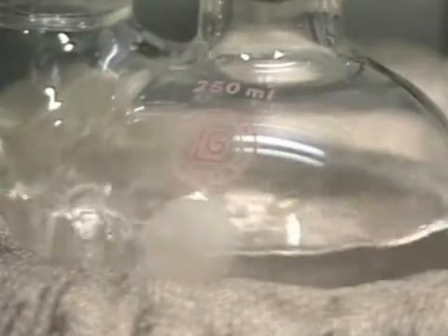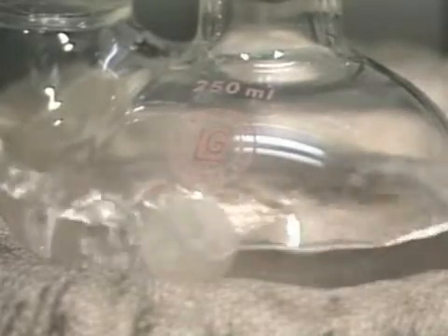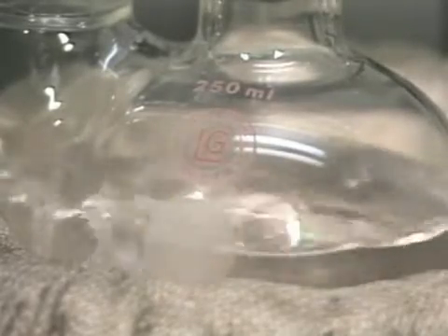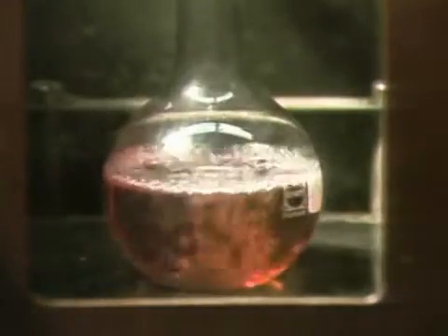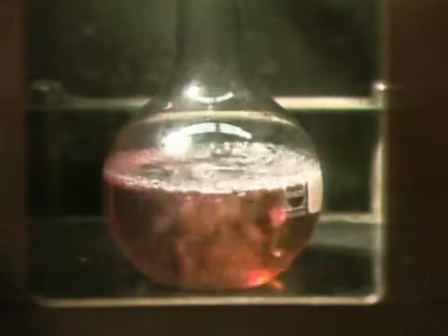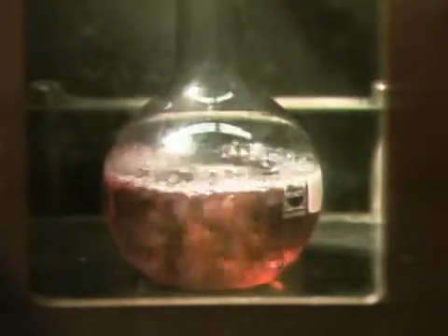Whether a reflux ratio is high or low depends on the design of the column and the mixture that's being distilled. For example, this mixture is made up of components that are hard to separate. A mixture whose components are hard to separate generally requires a high reflux ratio. On the other hand, a mixture whose components are easier to separate generally requires a lower reflux ratio. Maintaining the proper reflux ratio for a system is important because it can affect the equilibrium between the rising vapor and the falling liquid in the column. If that equilibrium is upset, the performance of the column will suffer.